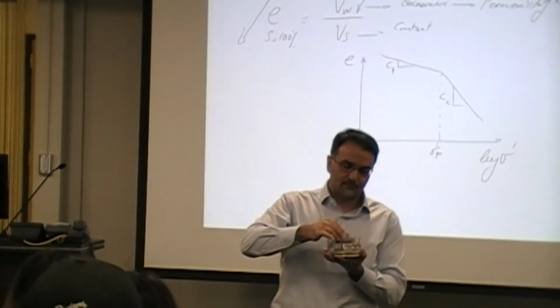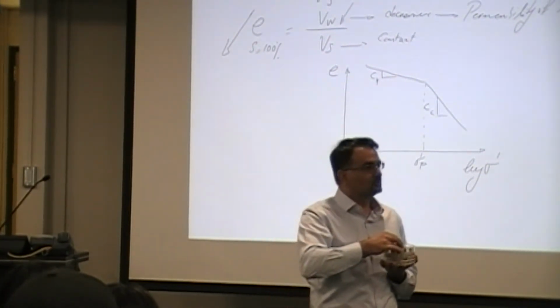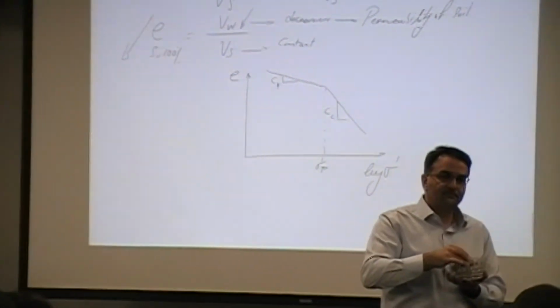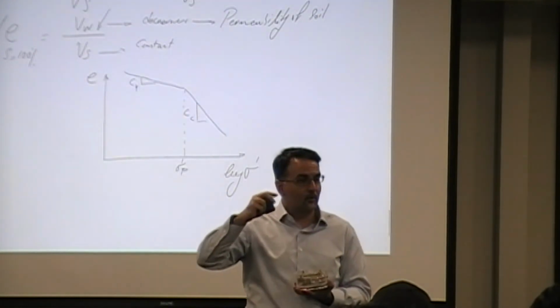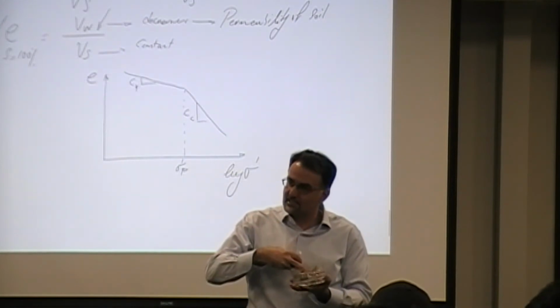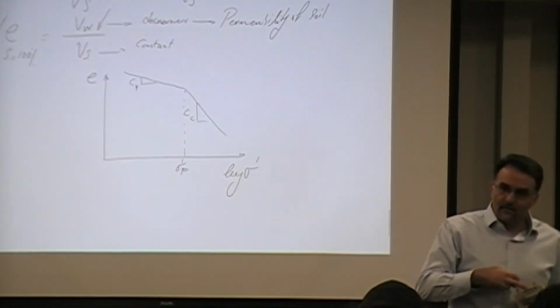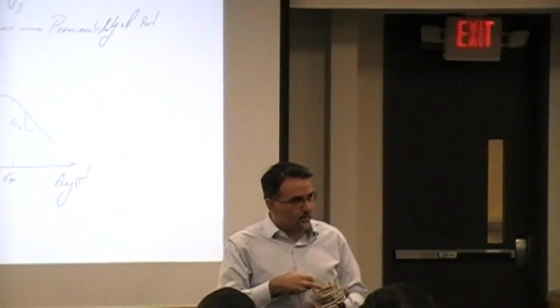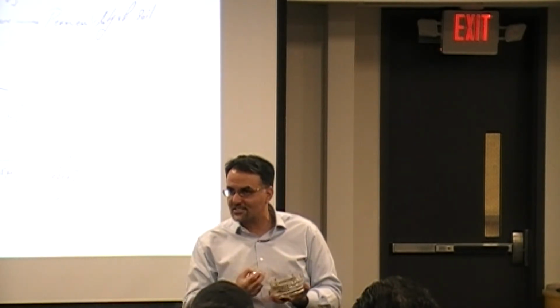We're going to talk about that. So essentially what you do is you place a, let's say, a weight of 100 grams at the top, right? And let it sit for 24 hours. What happens? The soil is fully saturated, you apply the load based on the curve that you see right there. What happens to the void ratio? Goes down, right? Why? Because you see settlement. What is that settlement a function of? Fully saturated, there is no air in there, there is no compaction, if you will, right? Therefore, it's all going to be associated with the escape of water.